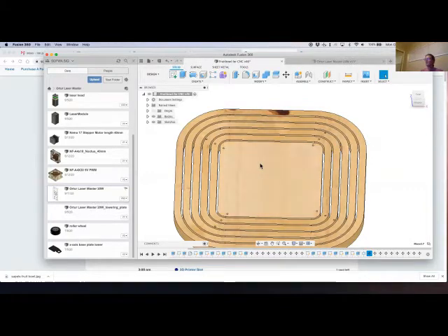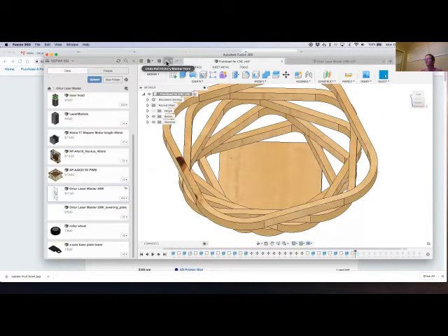I tried a few things. I thought maybe the extra edges from doing the chamfers were causing the problem. But when I took the chamfers out and redid the holes, they were still unreliable. But it also looked like the dowel pins weren't centered. They were slowly migrating towards an edge.